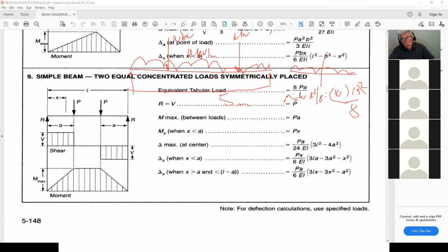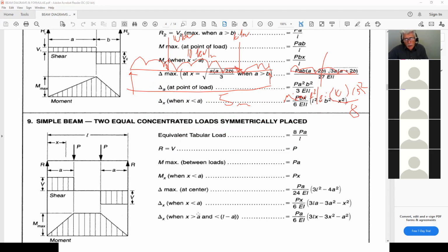I'm not going to do it, but therefore, the way it applies for deflection, it applies for moments, it applies for shears. So for example, if I calculate the reaction here, the reaction here is simply equal to P, and then the other one was WL over 2, therefore I add my P and my W, and I will get the total reaction, and so on. So I can use these things to do whatever I need to do, and where these things are very useful is that it really simplifies your life, like to calculate your maximum moments and so on, so that you don't have to go ahead and do shear diagrams and moment diagrams for a whole bunch of things.